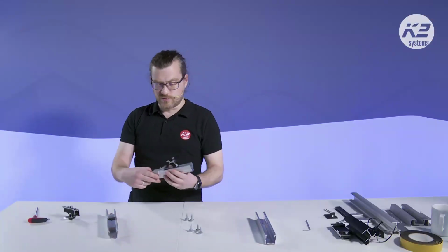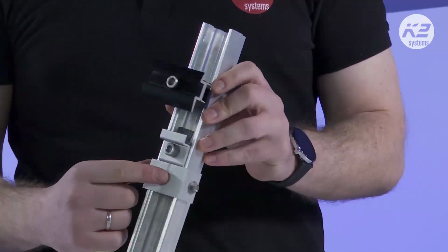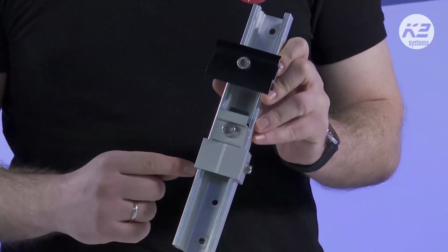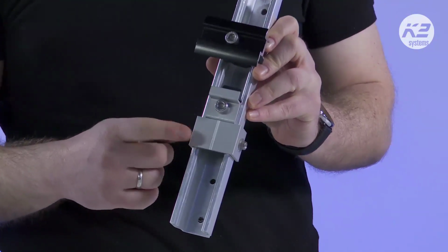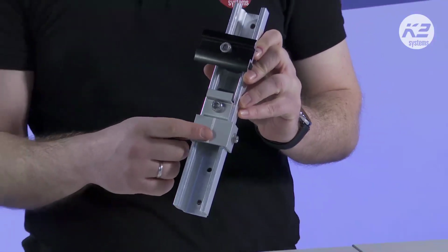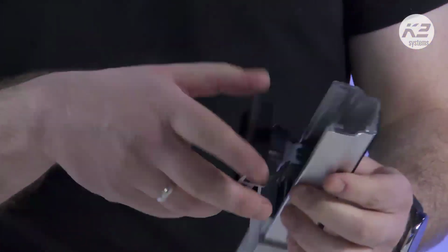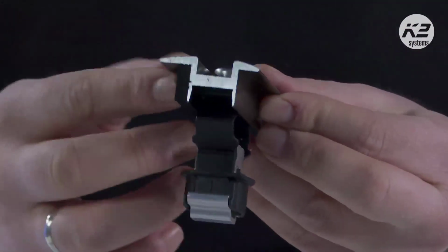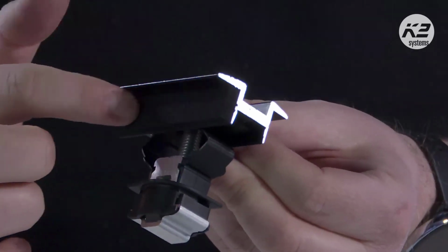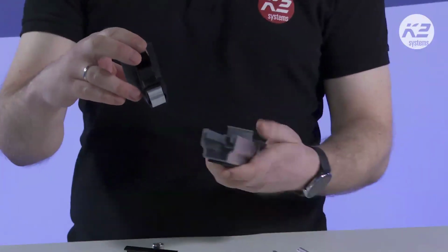And one additional component is this anti-slip clip. It's just screwed in on the second row from the bottom on the module field. So only in one row of multi-rails you install this anti-slip clip. I'll show later on our model. It's just screwed inside the multi-rail. What is also new is this facade clamp. You will see that it's a bit longer on one side, with additional sealing here. But the rest of the clamp is the same.